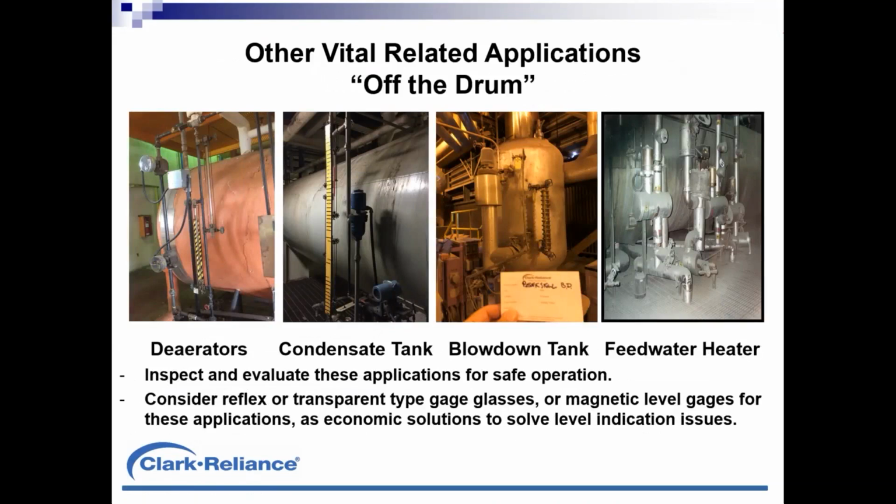Don't neglect these devices. They should be cleaned, inspected. If your plant has been down for COVID, many plants were shut down, closed, and being restarted. If plants were idle, you might want to take a little extra time to check all these instruments, making sure that your piping is clean, free flowing. When you blow something down and close the valve, make sure it responds promptly to the water level.